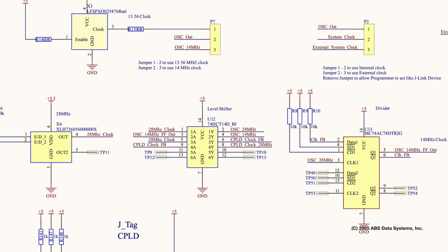On the next clock, I take pin 6, which is the inverted value, and feed that back into the flip-flop on pin 2. On the next cycle, the value present on pin 5 is now the inverted value. As this continues with each cycle, you get a stream of data alternating between 1s and 0s. Since this is occurring based on the 28 MHz clock, you get half the number of cycles, or 14 MHz.